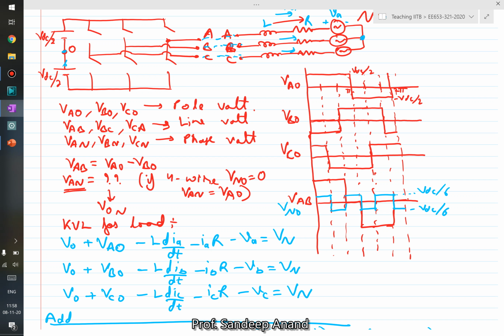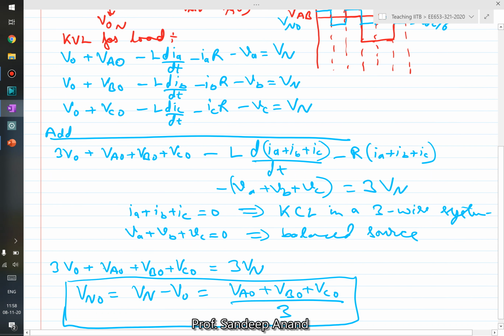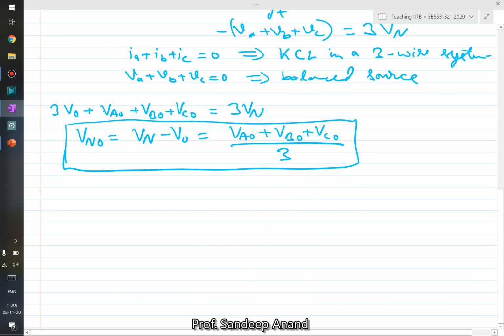Now, if you want to draw the phase voltage VAN, we can say VAN is equal to VAO minus VNO.